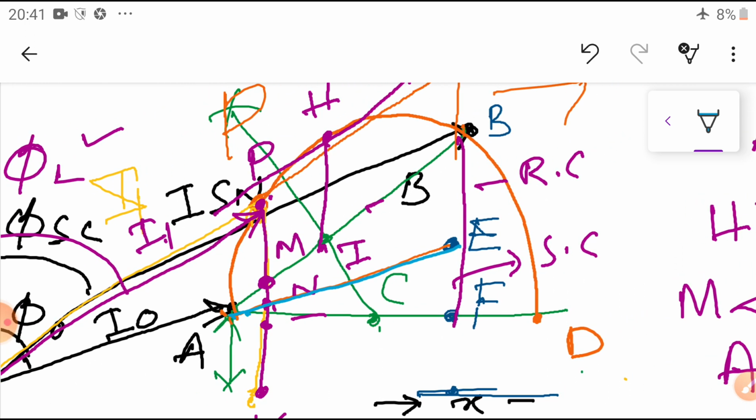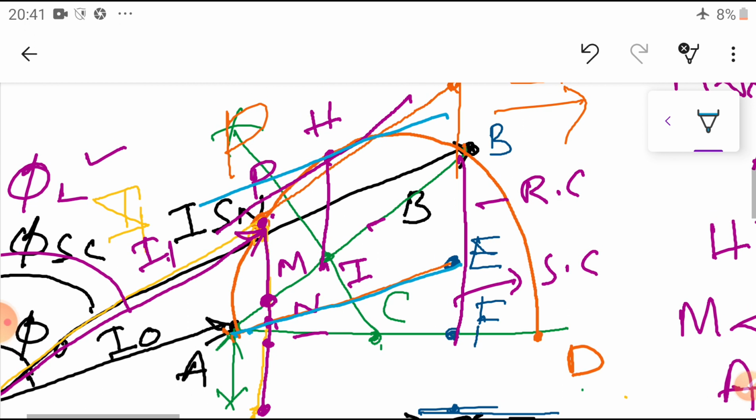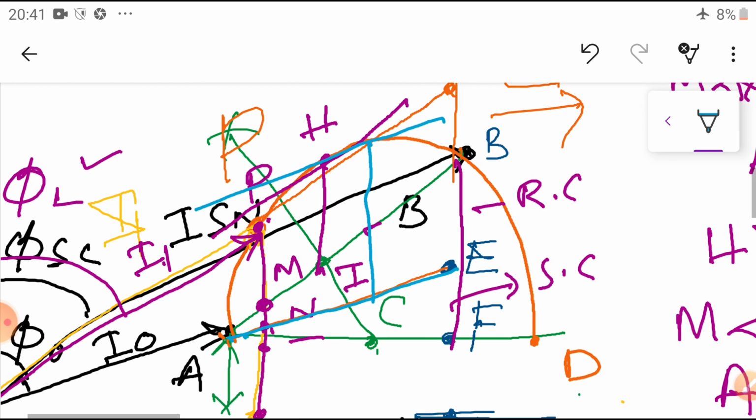So, what you are going to get? You are going to get one line tangent to this one. Then draw a tangent line from this one. Draw one vertical line up to the torque line. Okay, this is known as the maximum torque line. Where it touches here, you represent this touching point as R.